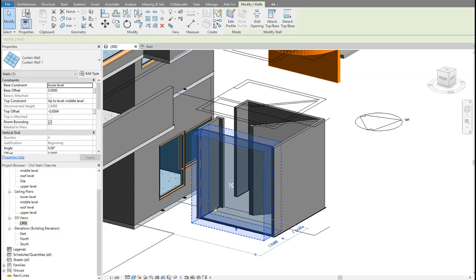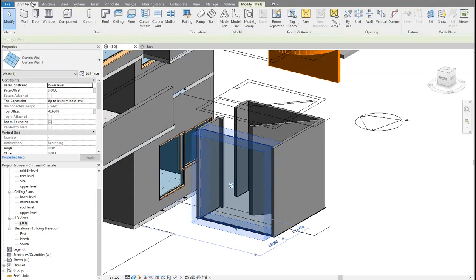So the special thing in curtain walls compared to normal walls is that it has what you call grid and mullions. And these mullions follow the grid. You cannot draw a mullion here, for example. Mullion, that piece of aluminium, you see them in the facades. Like even UCSI, many facades have mullions. It's like big glazing, and there are mullions like this, vertical and horizontal.